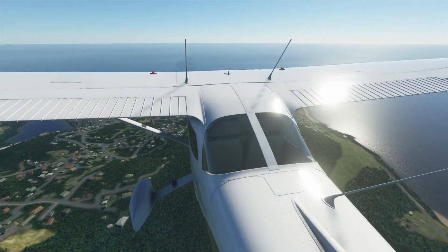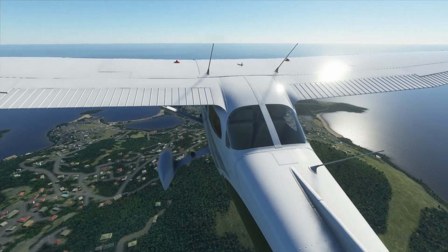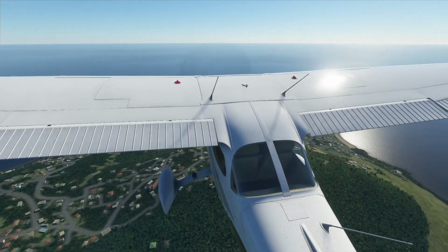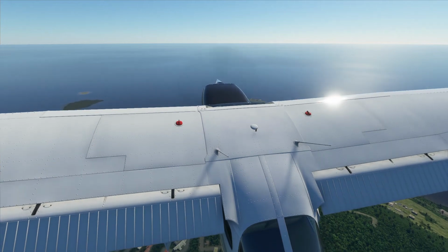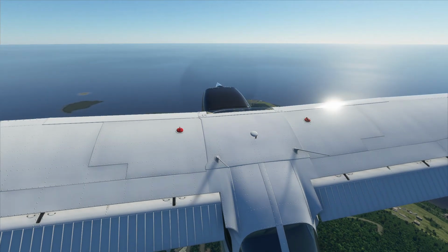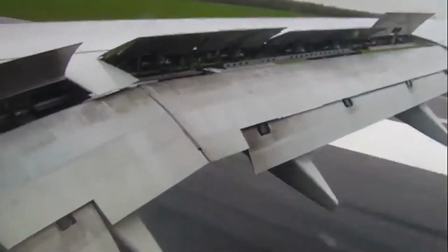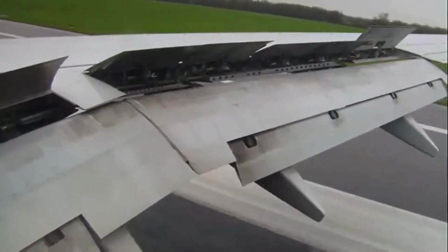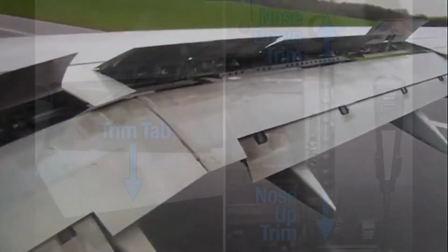Now let's talk about secondary flight control. Flaps are the most common high lift devices used on practically all airplanes. The flaps are normally flush with the wing surface during cruising flight. When extended, the flaps move simultaneously downward to increase the lifting forces of the wing for takeoffs and landings. On some airplanes, high drag devices called spoilers are deployed from the wings to spoil the smooth airflow, reducing lift and increasing drag during landing. They are also called speed brakes.